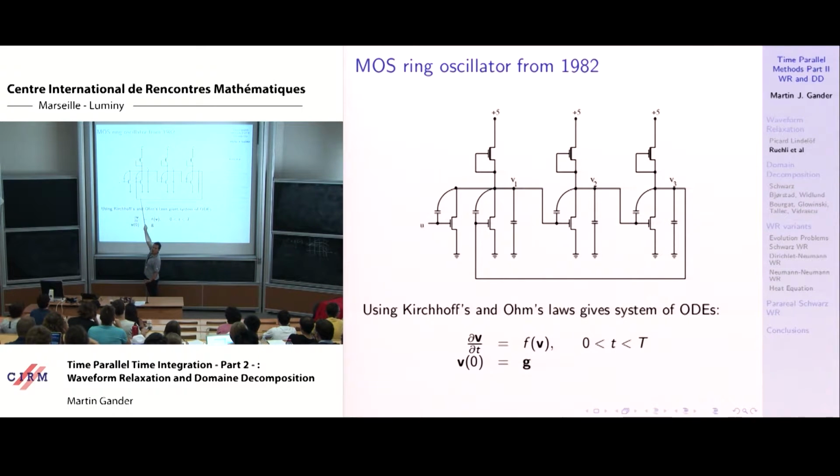This means this transistor will open. So we had 5 volts there, but because it will open, it will connect to ground, it's going to go down to 0 volts. And now you can see how it oscillates. 0 is going to close this one, it's going to pull up to 5. It's going to open this one, it's going to pull this down to 0. It's going to close this one, it's going to pull up. So this is why it's a ring oscillating circuit.